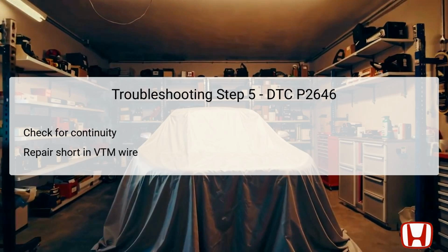The technician then checks continuity between designated test points, specifically between the PCM connector and body ground. A successful continuity signal suggests there is an issue, such as a short within the wiring leading between the PCM and the switch, signaling the need for repairs.